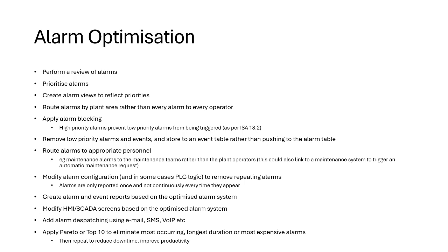So if you have too many alarms, then that just means that the operator can't cope with the volumes of alarms coming into the system. The actual number of alarms will vary from case to case, but 2 or 3 alarms per hour would be a good number for the operator to be able to act on, and also still be able to perform their usual activities.